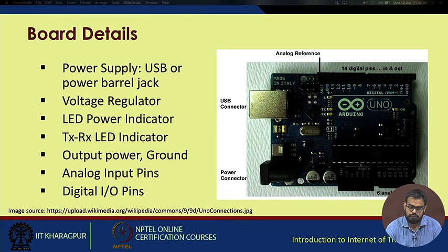So the board details are, as you can see from this figure, you have a USB connector to which you connect your Atmega board to your PC. The best thing about this is the interfacing is very easy. You can connect your Arduino based board to either a Windows based PC or a Macintosh or a Ubuntu or Linux based system. So this is the USB connector. Then you have the power connector to power on the device in standalone mode. Otherwise, if you connect it to a PC, it draws power from the PC itself.